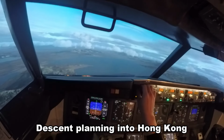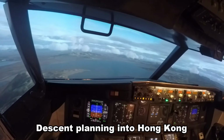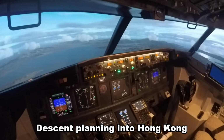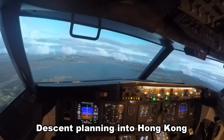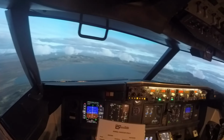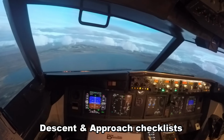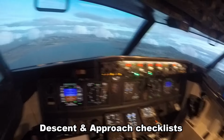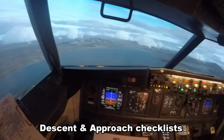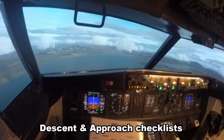and we'll just set our minimums. So to radio altimeter 200 feet as our minimums. Now we'll have full stop landing, auto brake set to 2. So we'll have a descent checklist: recalls checked, auto brakes setting 2, landing data VREF of 135, minimums 200 feet, approach briefing completed, descent checklist complete. Approach checklist, altimeter is QNH 1009, approach checklist is complete.